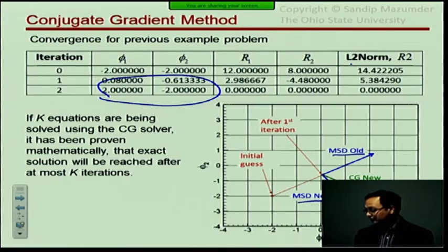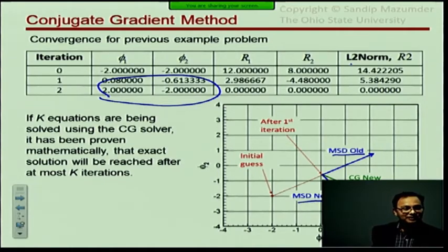Now, the big downside, of course, is that this is only true for symmetric matrices. Okay? And that's where, when this first came out, it was great, and then people said, oh, but we can't use it for practical problems, because if we have non-uniform mesh, we'll break the symmetry of the matrix. If we include fluid flow, we'll break the symmetry of the matrix. If we have non-uniform transport coefficients, we'll break the symmetry. If we have curvilinear grids, we'll break the symmetry. So what is left? Okay?